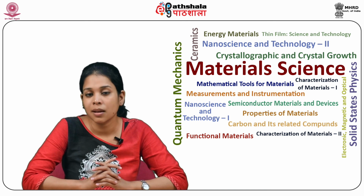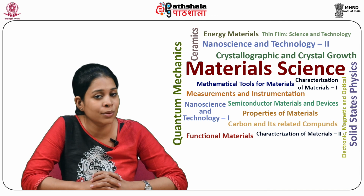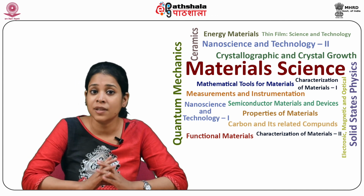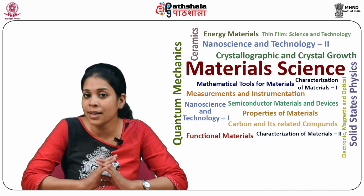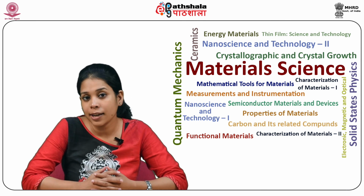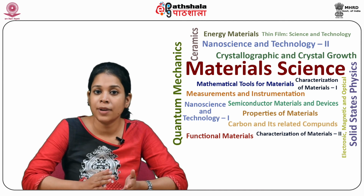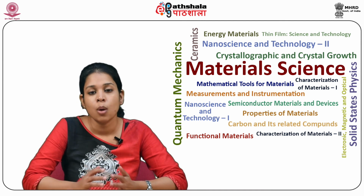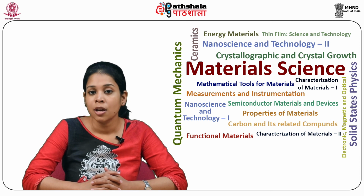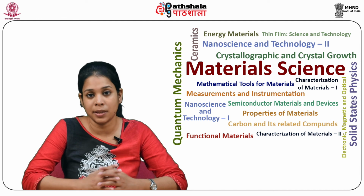So students, let's now summarize what we have learned in this module. We have discussed that there are three types of polarization: electronic, ionic and dipolar. The electronic polarizability increases with the size of the ion, so the bigger the ion is, the higher is the polarizability.